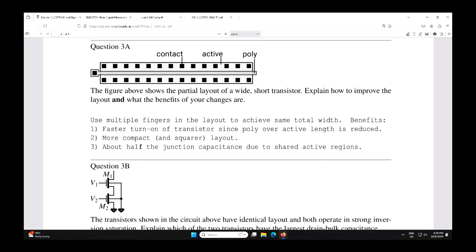Physically you can put it on the gate if it's off the well, so it must be something to do with the modeling or something. It's a manufacturing issue, and there's probably also a stress issue. If you put a contact on top, you're going to create stress under the gate, and that is going to mess up your MOS structure. You build in stress deliberately, but you don't want stress that is not intentional.